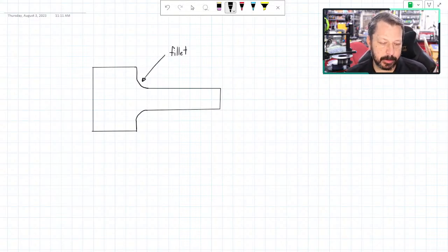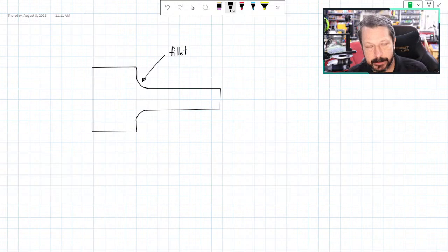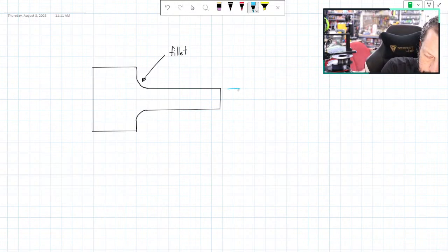And what I've drawn is pretty extreme on the rounded side. They do approach a sharper corner than what I've drawn here typically, but there will be some transition there. And we want it to be generous enough, or smooth enough, that it doesn't create super high stress concentrations. So let's put dimensions on here. Let's put that one over here.